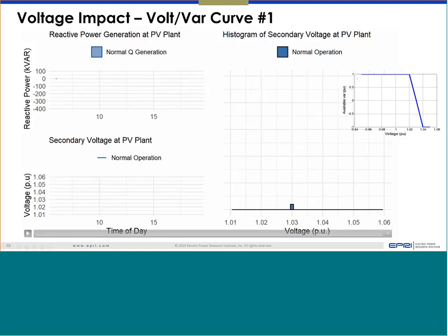You can clearly see this Volt-Var is, again, no dead band. The reference point is much higher, 1.03 is the VREF point. So the voltage was pushed in the higher direction, with a very aggressive slope. If 1.03 is the VREF, by 1.04 it went to its maximum. Compared to other situations, it's a pretty aggressive Volt-Var slope setting.